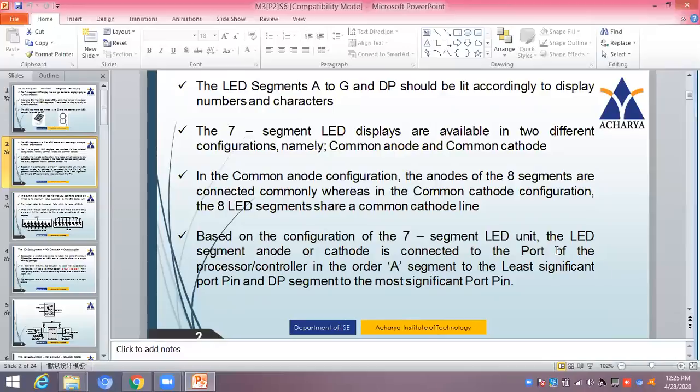Imagine an application wherein the processor wants to send some data to the LED. The processor will send it to 8255 and it will choose any of the ports. Assume it chooses port A. So the 8 pins of port A are used to send the 8-bit data, and those 8 bits of port A are connected to this 7-segment display. I'm telling it in a very simple way.